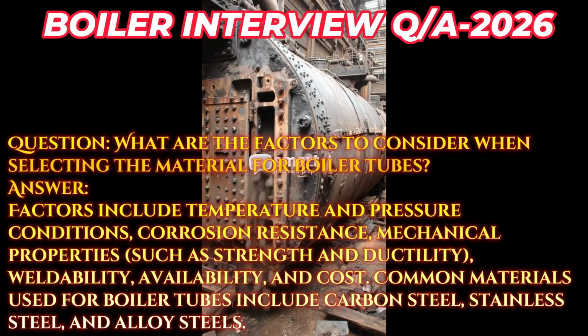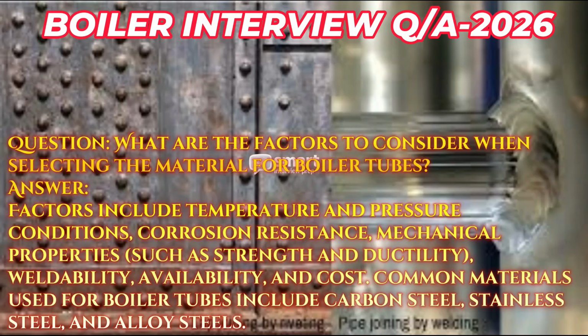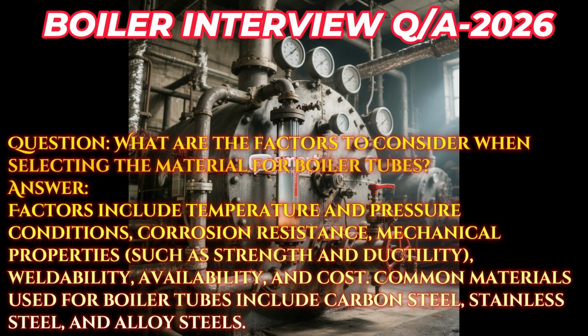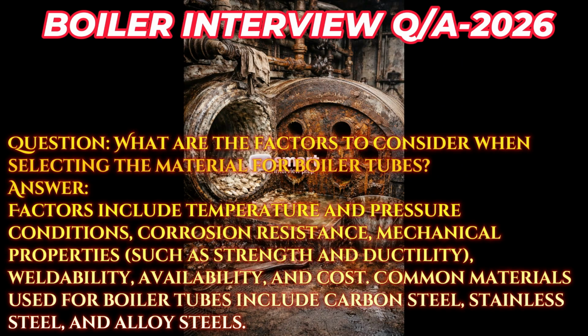Question: what are the factors to consider when selecting the material for boiler tubes? Answer: factors include temperature and pressure conditions, corrosion resistance, mechanical properties, such as strength and ductility, weldability, availability, and cost. Common materials used for boiler tubes include carbon steel, stainless steel, and alloy steels.